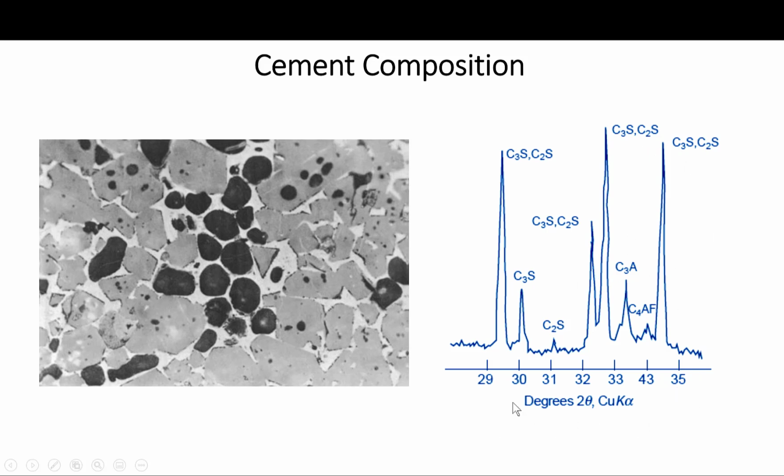This is the result of an XRD analysis using some quantification method. As I said, the internal standard method, where you have some internal standard, typically titanium oxide, that you mix with your sample, will serve as a reference to compare the peaks. You get the relative quantities of each of these phases.